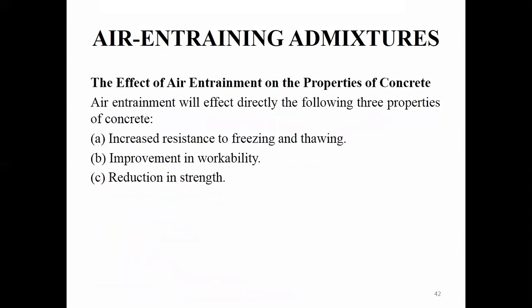Okay, next we are going to discuss the effect of air entrainment on the properties of the concrete. Here we have so many properties. Majorly we have three: one is increased resistance to freezing and thawing, second is improvement in workability, and finally we have reduction in the strength. Okay, let us discuss one by one. First, resistance to freezing and thawing.